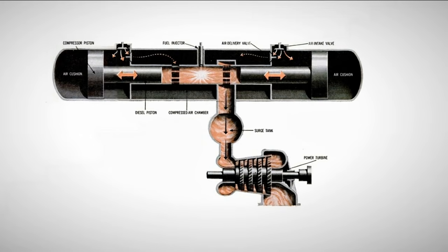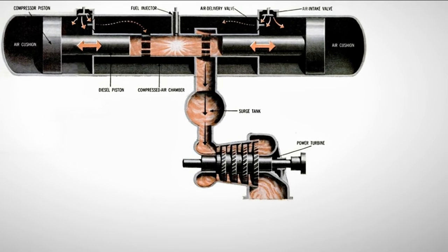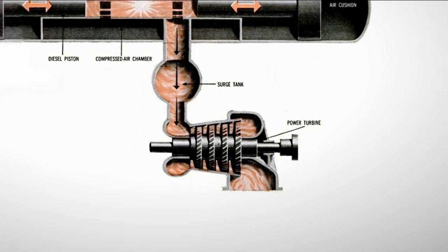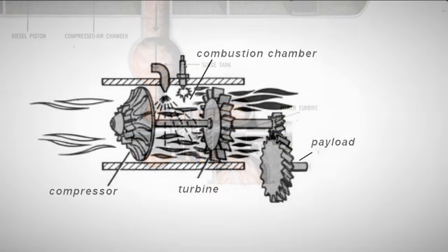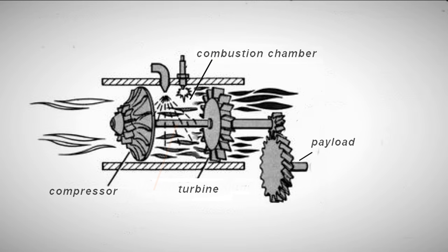The traction turbine was significantly smaller than in conventional gas turbine engines of equivalent power, since all of its power was efficient. In a conventional gas turbine engine, the compressor is typically mounted on the same shaft as the turbine. So the turbine transfers its power not only to the payload but also to drive the compressor. This power transfer is quite significant, approximately 70%.